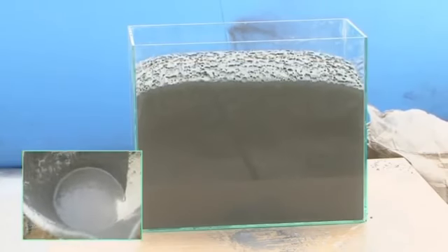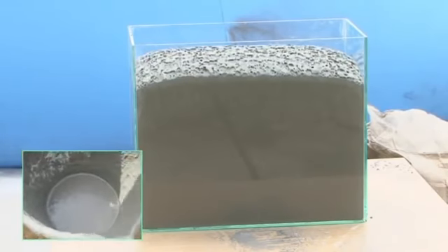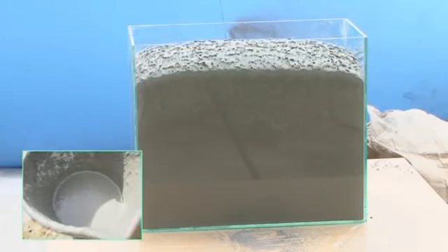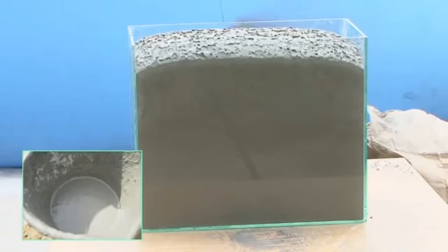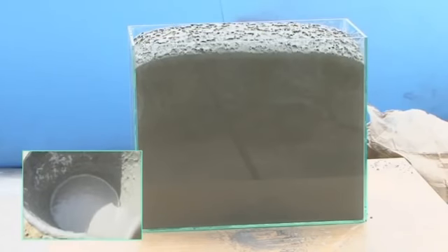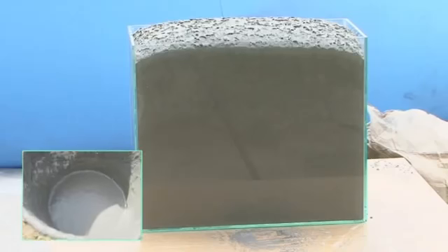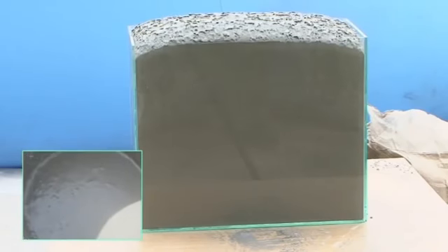The ratio of water to dry mixture for preparation of the suspension depends on the application and is determined by trial. As a rule, this ratio is in the range of 30 to 90 liters for each 100 kilogram dry mixture.